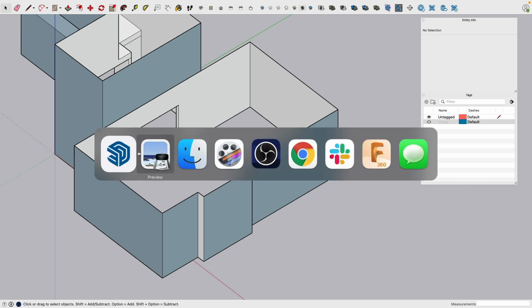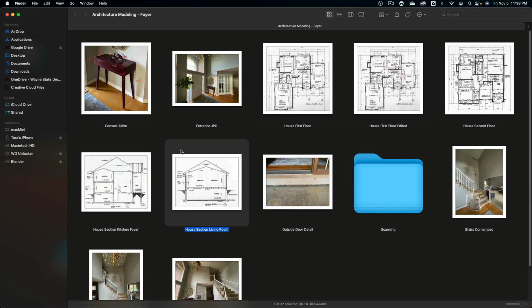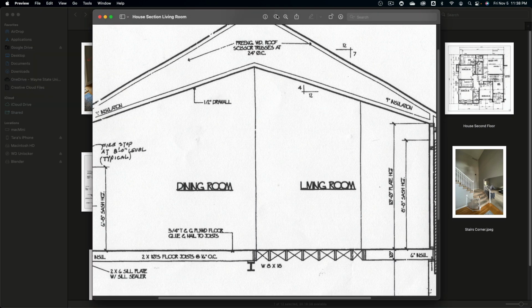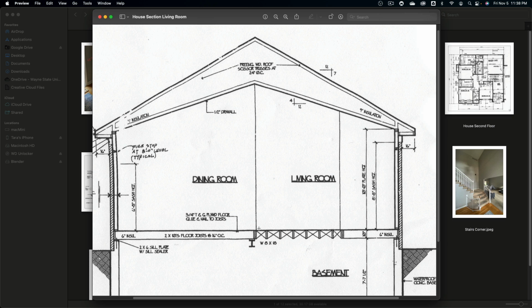When we go back to the image, I think we have it in here. Yeah, so there is actually a midline, but we don't really have a height. There's no degree for this line. There actually is. Look at this. See this? 4 over 12. What's this ancient technology meaning? That means we have 1 point, 4 inches down, 12 inches over, second point, and that defines the angle.